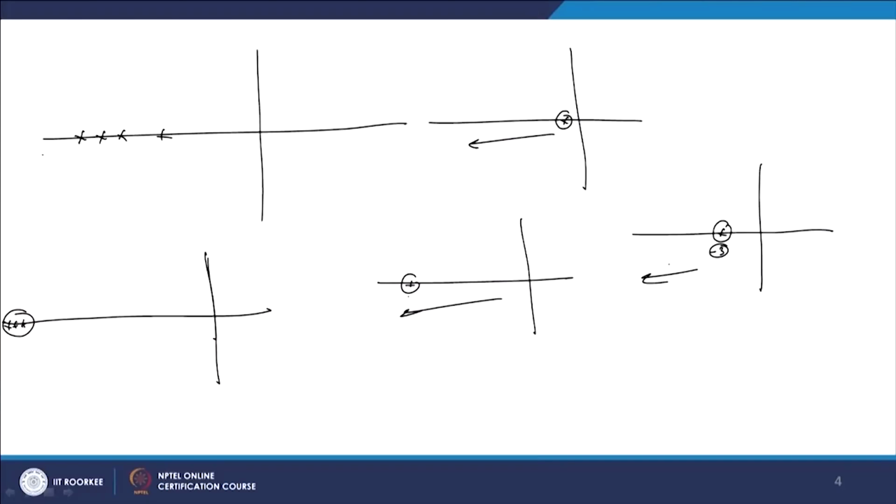That means you have to move the poles to the left side when there is a requirement. If you want to reduce some control energy, let us say one pole is on the right hand side, this is 2, you can shift it to say -2. So the original system has a pole at 2, and if you move it to -2, we require very less control energy. So that is a thumb rule we can also use.